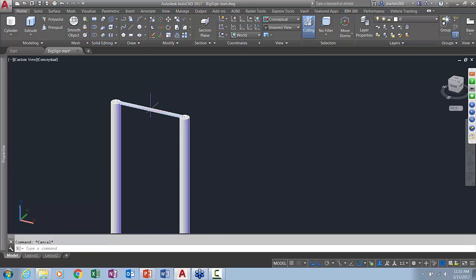So I'd like 2 of these, so we will copy this one down. And when I copy it down, I've got my ortho locked. You can see that as I copy that, I just picked a point in space there, and I can drag this in all 3 axis directions. In fact, you can even see that's -Z. Let me pull this down 2.25 feet apart. I want those.